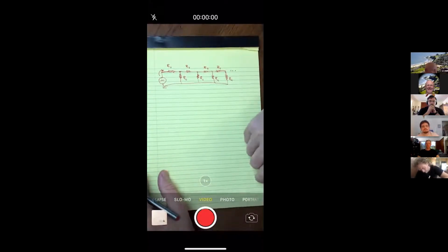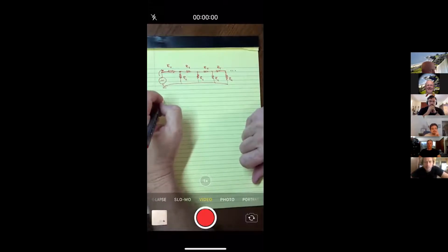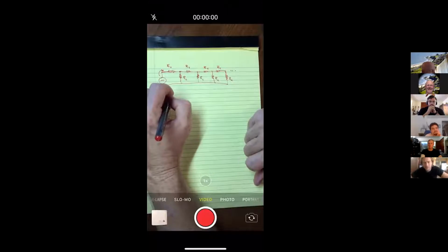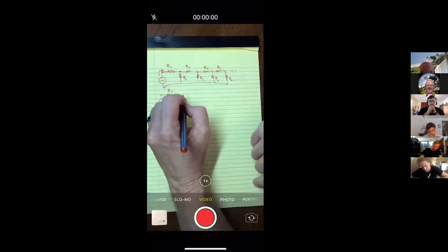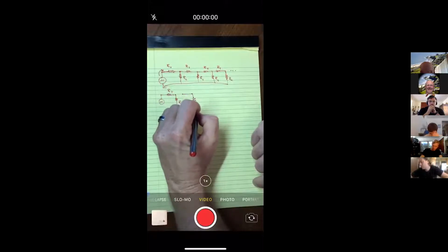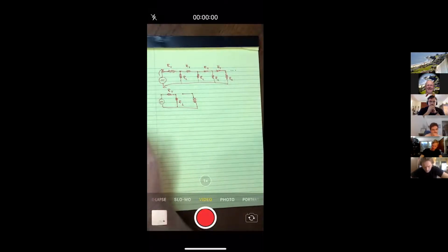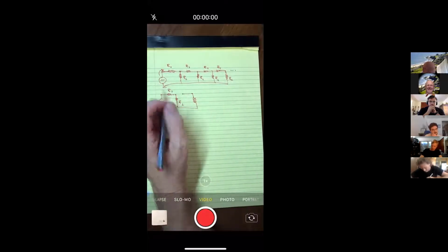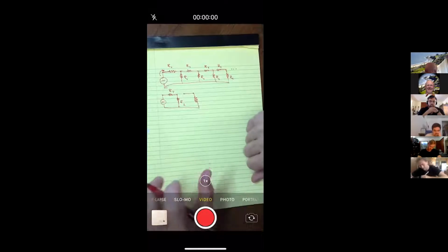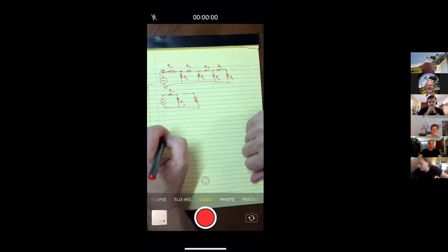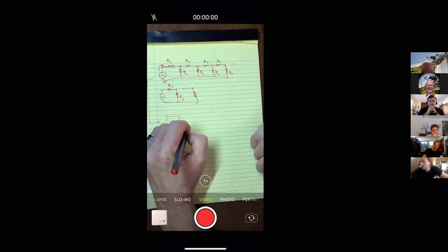But when you have a lot of subscribers, sometimes some things interesting can happen. And so here's kind of the thought process. Go ahead and let's look at just the first subscriber. And then say something like this, that the rest of the subscribers after the first one, and so the second out to infinity, is some other value. Okay, let me not give it a name yet. Let me just say there's some value there. But here's the neat thing about infinities, because what we're trying to actually do is say, what is all the subscribers equal to? And so that's the equivalent resistance.